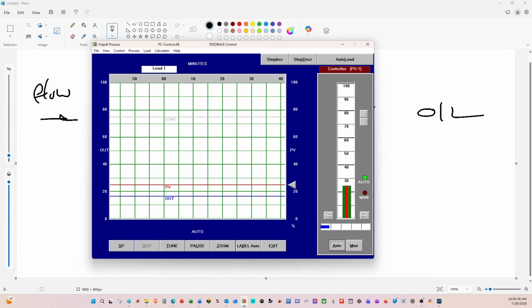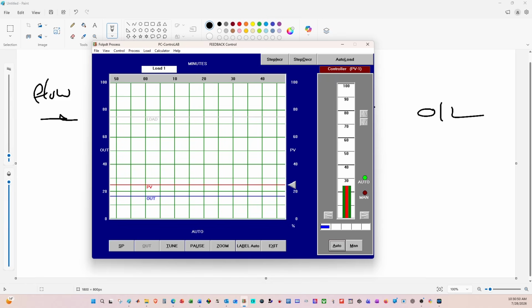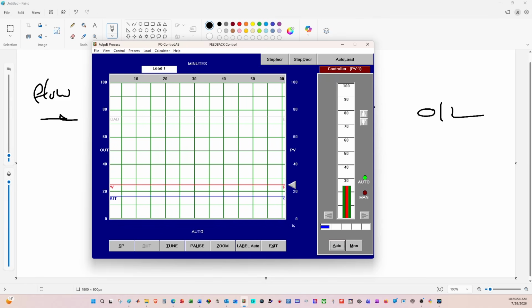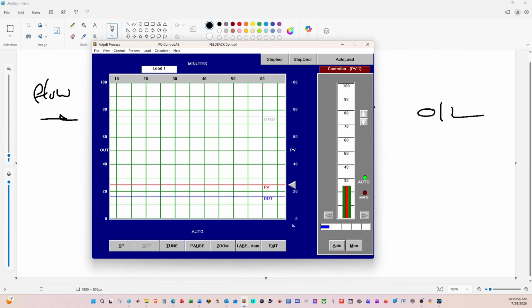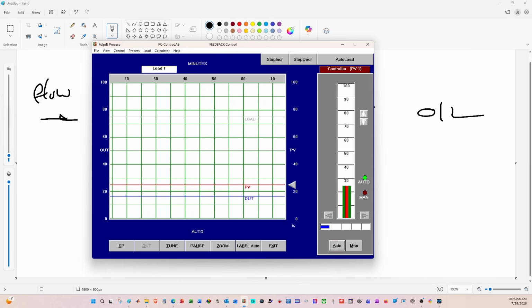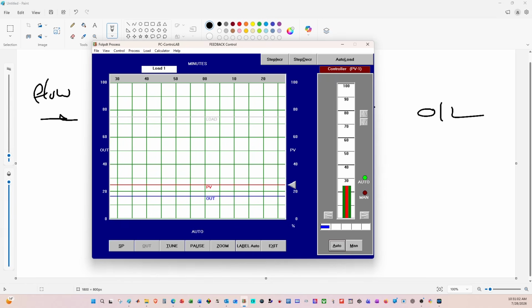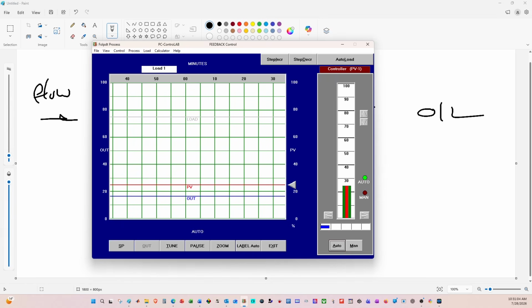You might have a temperature controller that is in the manual mode and the process variable is sitting at 150 degrees Celsius, but the set point is at 120. As soon as the operator goes back into auto without any tracking, the controller is going to see that there is a 30 degree error and it's going to start to open or close steam valves. Let's demonstrate this.